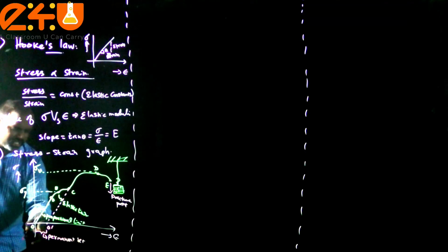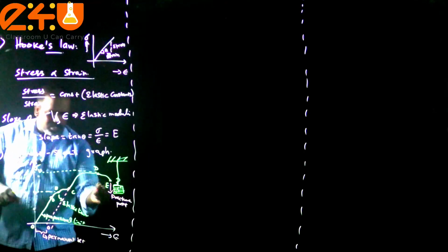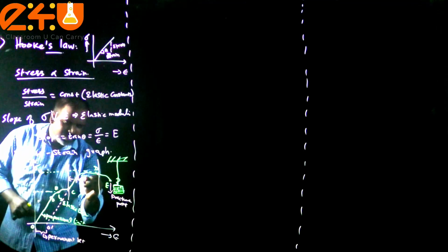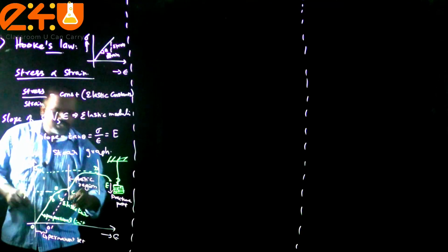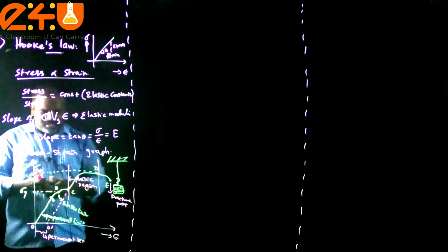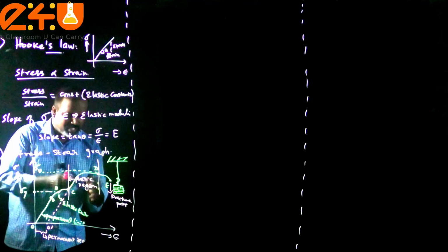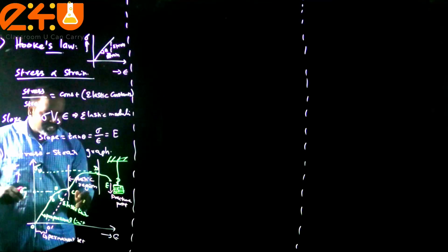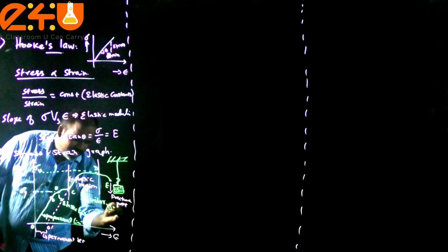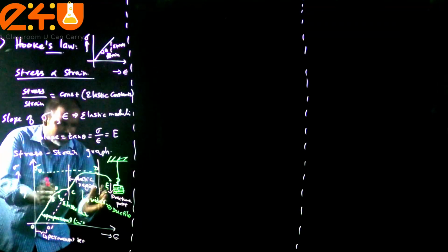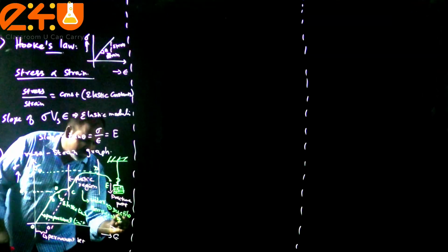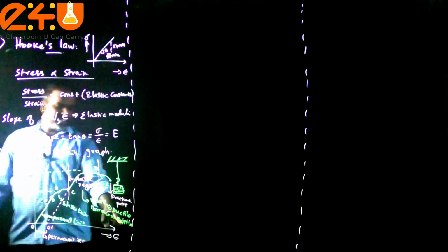This value is generally less than 0.01%. The region between C and D is called the plastic region. These graph related problems come in MCQ exams. If this plastic region is wider, the material is called a ductile material, meaning it can be made into a sheet or folded. If it is narrower, it is a brittle material and can easily break. Glass may be an example of this.